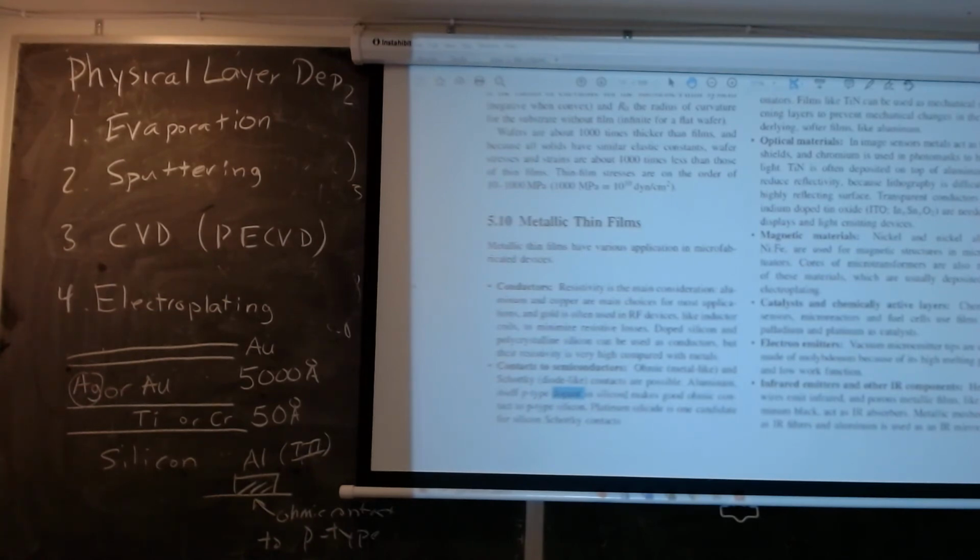Aluminum is a very interesting material in a lot of respects. There are whole textbooks devoted to aluminum. Aluminum is also a pretty good adhesive material. Not always. Certainly for some types of substrates, you don't rely upon its adhesion. You use other materials like titanium and chromium.